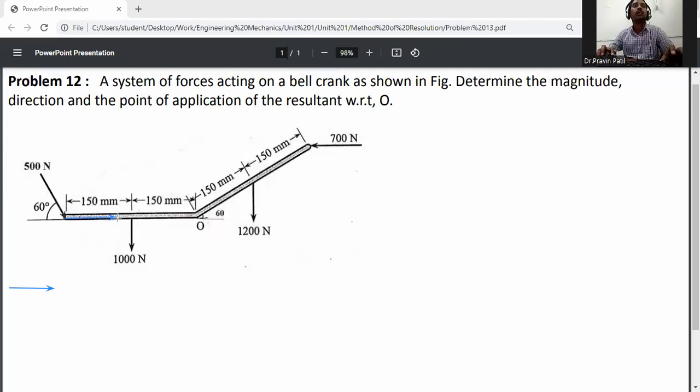One it is in X direction. Second one it is in Y direction. Okay. So actually, this is towards the point. So it is angle with respect to horizontal. So that's why on X-axis it will be 500 cos 60. On y-axis it will be 500 sin 60. Okay, this is your result.